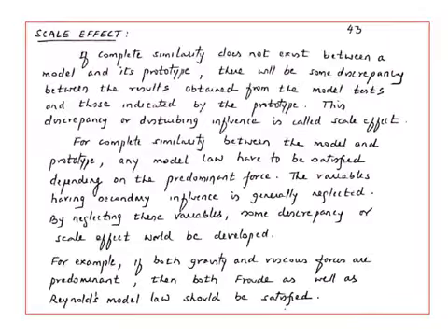So these are the problems that were discussed on undistorted models as well as on distorted models. There is one last topic on model studies, which is known as the scale effect. All this time I was discussing the dynamic similarity between the model and prototype, where one particular force was predominating. If viscous force was predominating, I was using the Reynolds model law, and if gravity force was predominating, then I was using the Froude model law. That's the reason why we have some scale effect that is taking place.